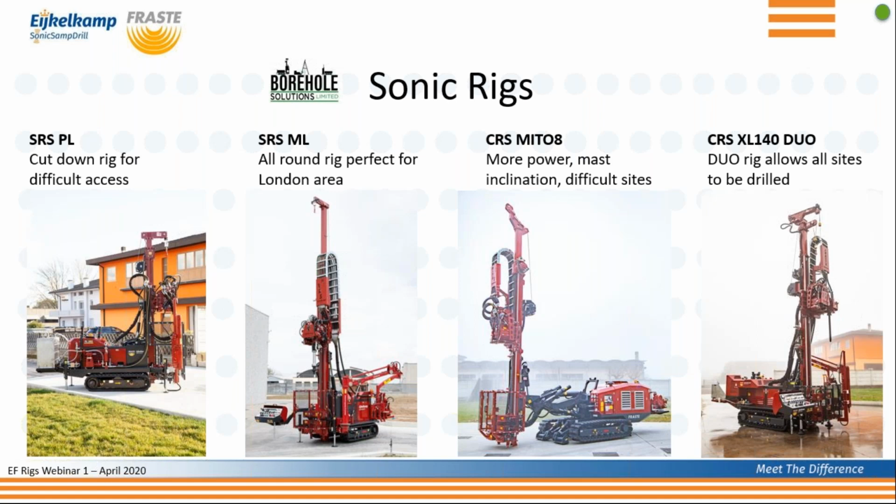We do a lot of dewatering with this machine. We do a lot of angle holes. Say, for example, they want to drill inside a building but can't. We'll set up outside the building, and then we'll drill at a slight angle and work the deviation out. Now, you can't do that with cable percussive, and in certain geology, you can't do that with standard rotary. So the reason why it has to be sonic is that this method works at an angle.